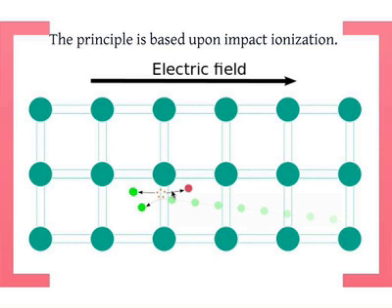So you have one electron coming in at very high energy. It hits an electron which is bonded to silicon, so it's in the valence band, and kicks it out of the bond. Essentially, this electron can come in and break the bond. Now you see what has happened is that when you break the bond, you've created an extra electron and a hole.